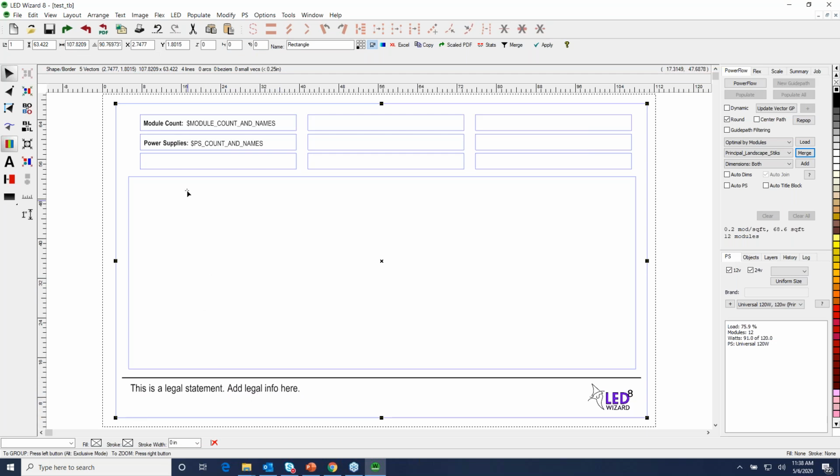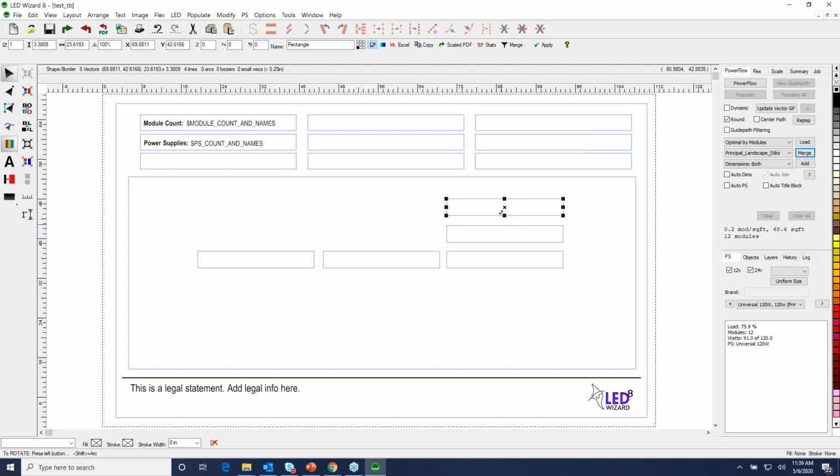That's pretty common. And then I created some text boxes up here, and again, this can be organized in any way that you want. I just drew text fields, and if you hold Shift and Control, you can copy a text field along a line so that they're perfectly aligned.